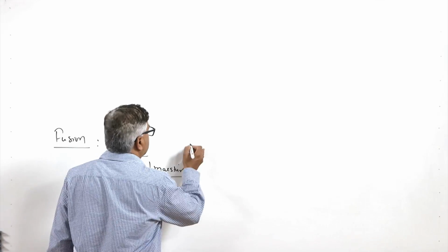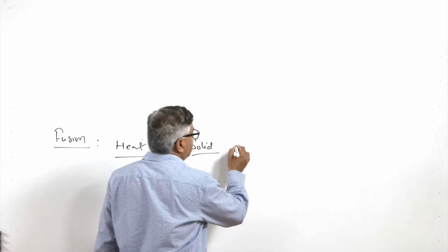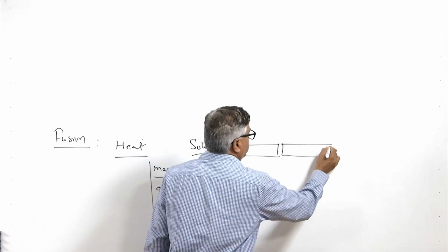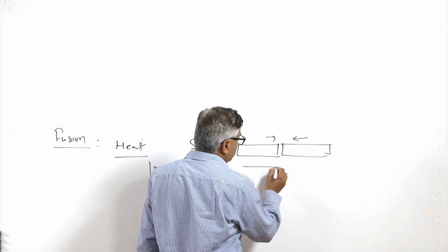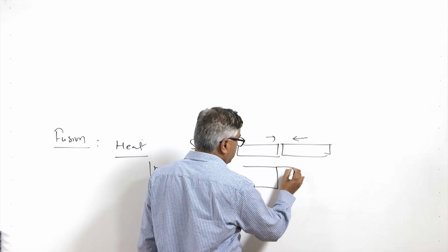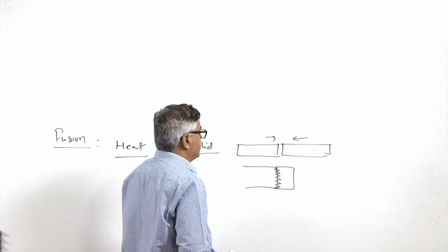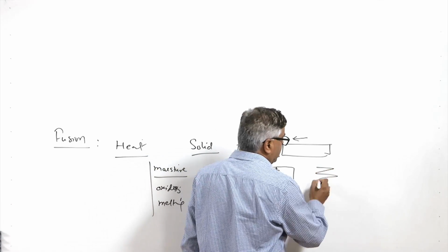If we consider the solid state joining processes, wherein the metal pieces are to be joined in the solid state, under pressure the two are brought very close to each other, so that the fixed surfaces touch each other very firmly, and the metal to metal contact is established through the deformation of the peaks and valleys at the surface.